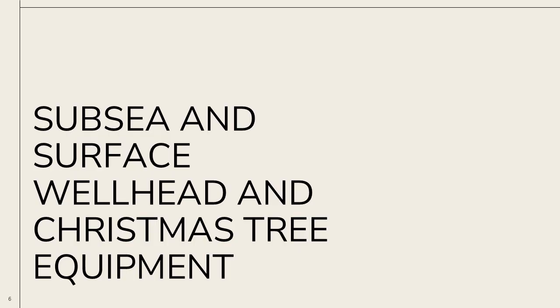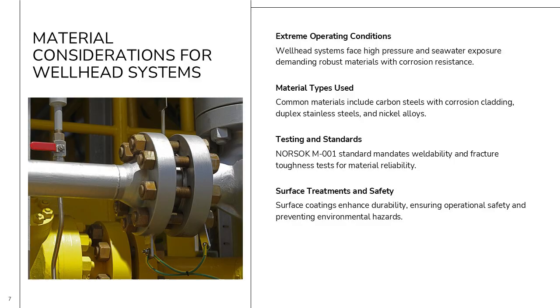Material considerations for wellhead systems. Wellhead and Christmas tree equipment operate under extreme conditions, including high pressure and exposure to seawater. Materials must exhibit excellent corrosion resistance and mechanical strength. Carbon steels with corrosion-resistant cladding, duplex stainless steels, and nickel alloys are commonly used.